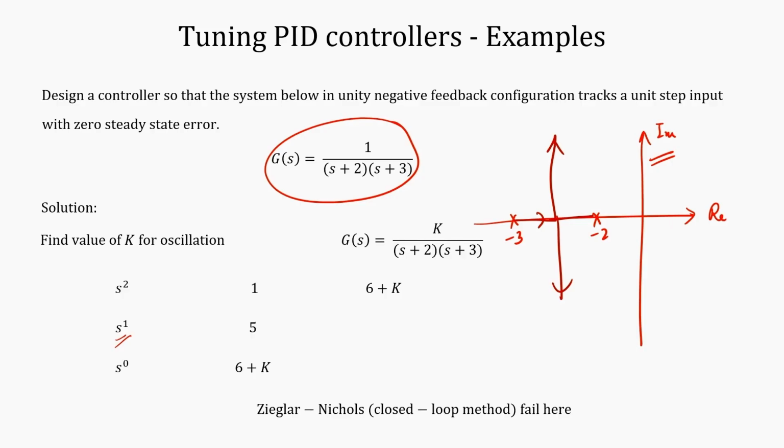And using that S curve, you can find the inflection point, find the tangent, and use that L and T value to find the value of the PI controller. This example shows you when to use which method. If you know the transfer function, then also you can take a call as to when to use which method.